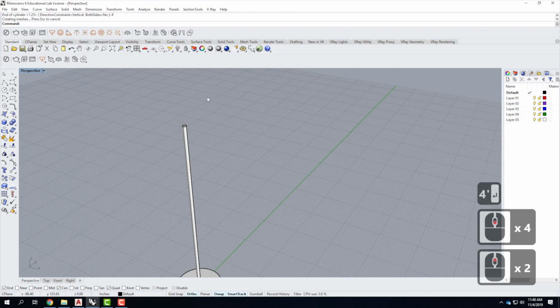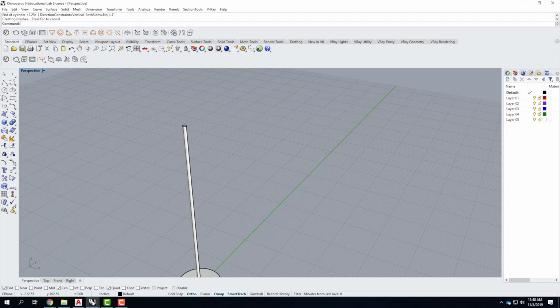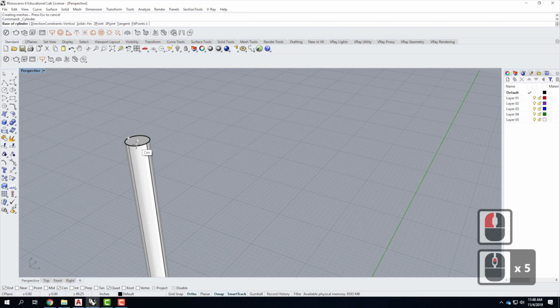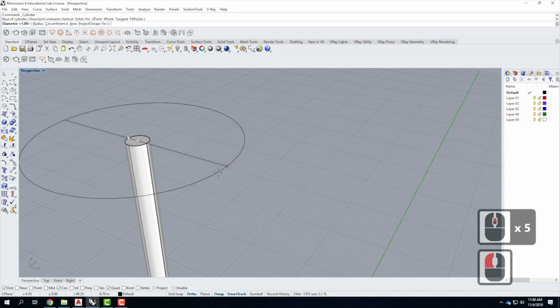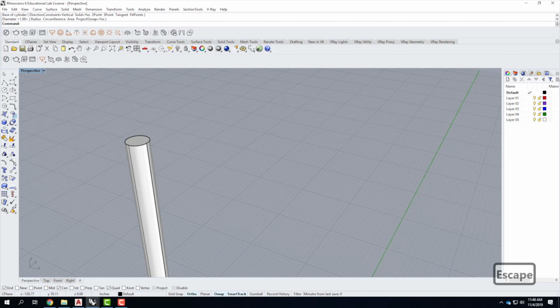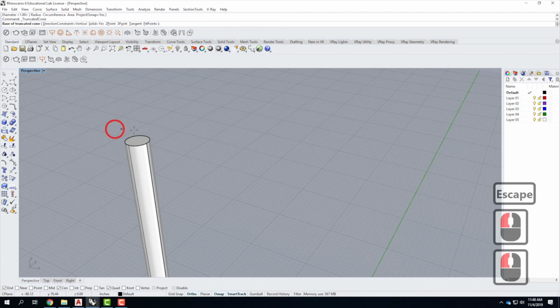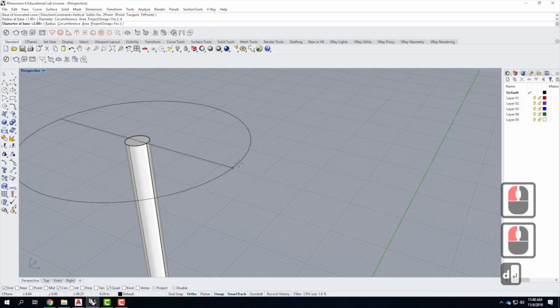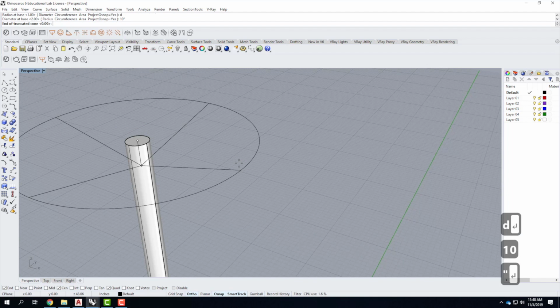I'm sure you guys can come up with better looking geometry than what I'm doing, okay? This is just purely the example. So let me come in here to the cylinder again. Let me make sure I'm snapping to the center. There it is. Let's say my diameter is going to be, you know what, let's make it slope instead of being a perfect cylinder. We'll do this. All right, so my diameter, we'll do it at 10 inches.